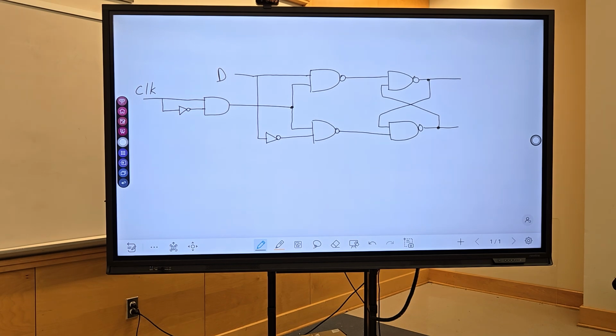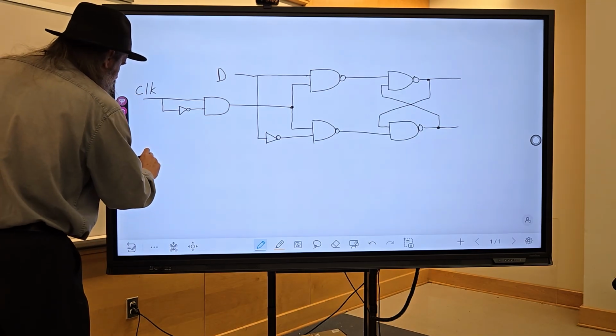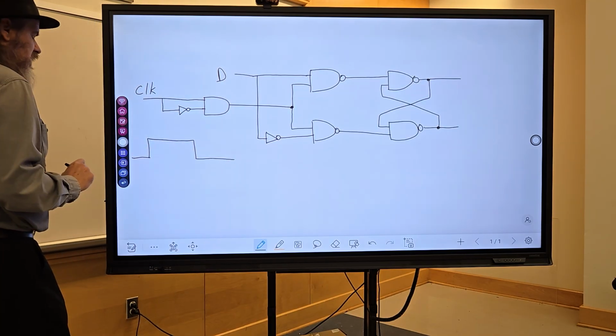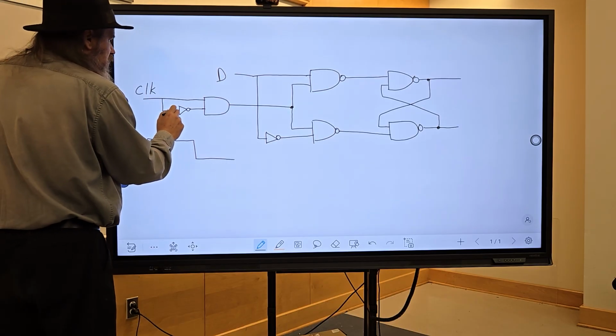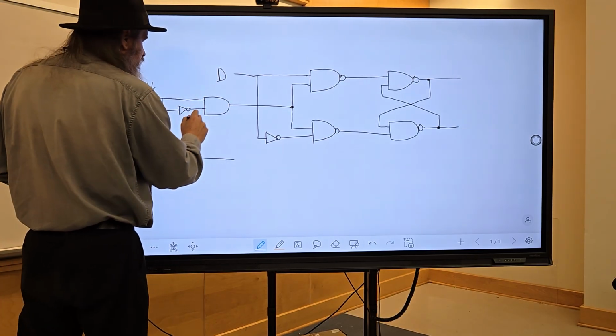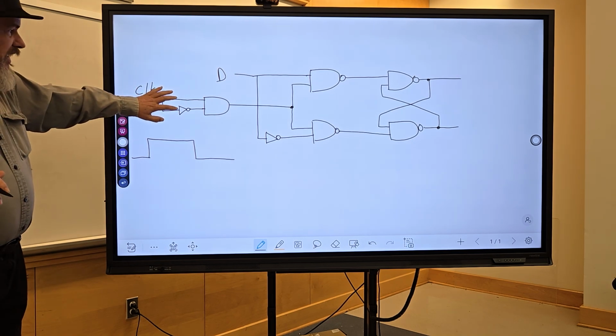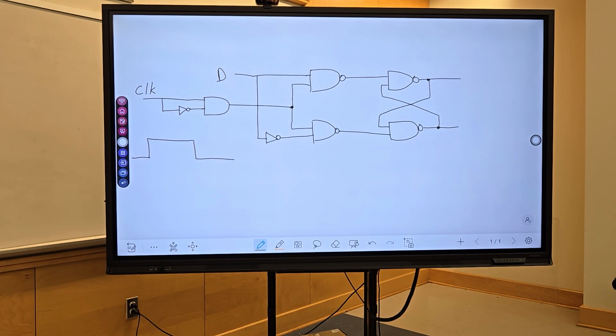Now we just saw the propagation delay of the inverter as low as 6 nanoseconds. So when a clock pulse comes here, say a clock pulse is this long, the AND gate is going to stay low, okay, because ANDing a value with its inverse keeps it low, it stays at 0, right?